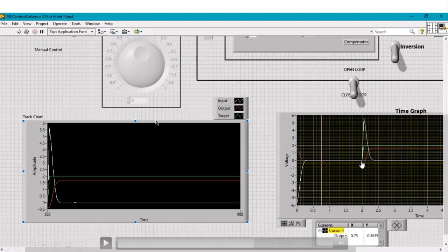The command came in at 2.01 seconds, 10 milliseconds, right? And it came in right here. Then this is the voltage that was applied to the arm. We actually have a 6-volt motor, so we shouldn't put anything greater than 6 volts. So anyway, when you look at the arm, what happened? It started from some negative position and went to a position that's slightly under.